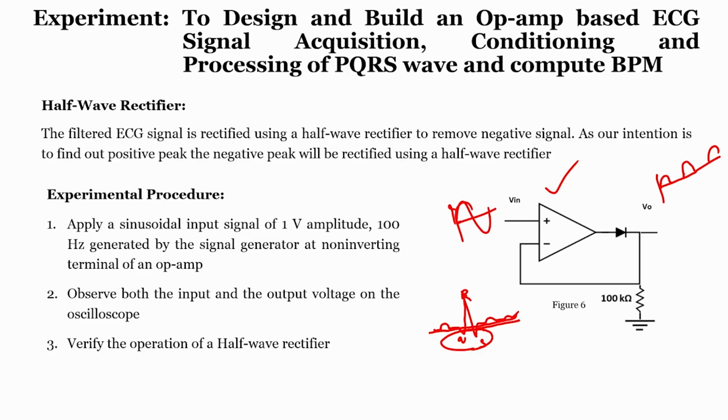As we know, if we keep a capacitor, the capacitor will charge to whatever output we receive. So, if the voltage is increasing, the capacitor charges slowly. Since we do not create any discharging path, whichever is the highest voltage that we get, the capacitor will be charged to that highest voltage value, that is good enough.